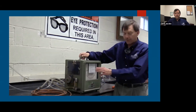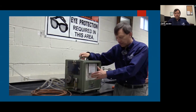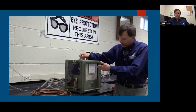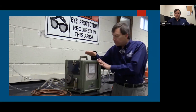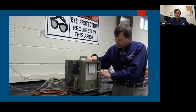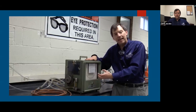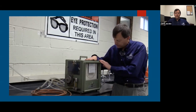And again, you're going to have the reverse happen. Now you're going to purge the gas out of the gravitometer. So once it starts purging, it will start moving back down the scale, back up the scale to 1.0. Now, in order to lock this needle up again, we have to have this pointer very close to the 1.0. Otherwise, the locking mechanism cannot engage and safely put the needle up inside the machine and protect it.